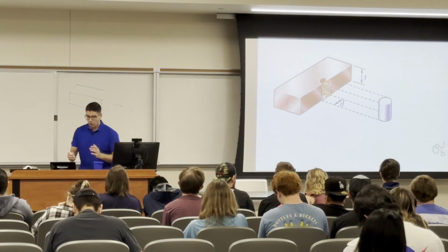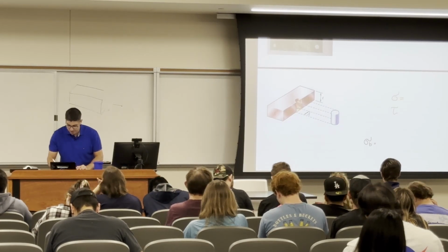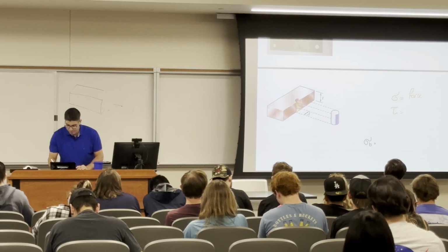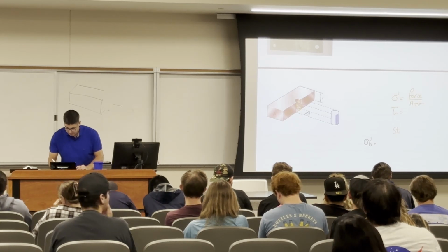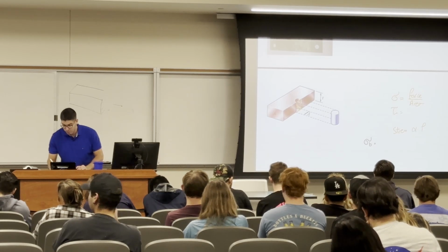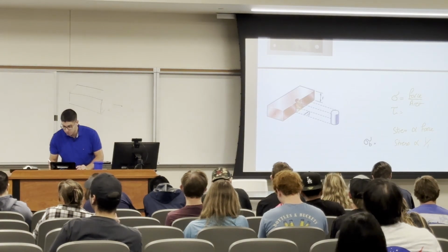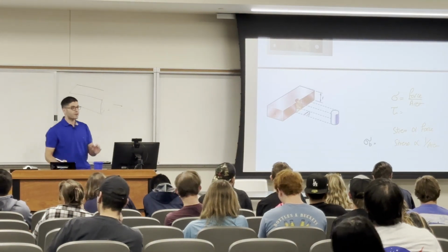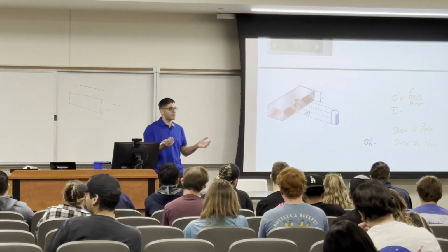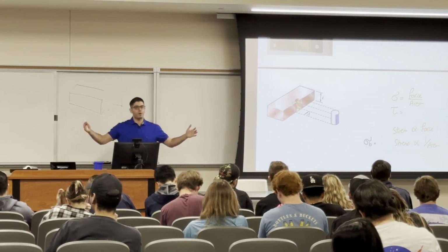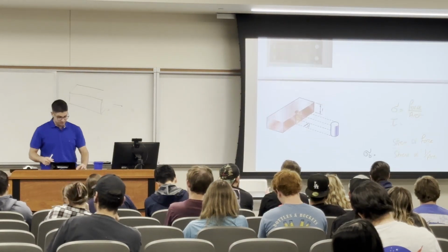Okay? You always look at the equation of the stress. Stress, or even the shear, is force over area. So the stress is directly proportional to the force, and inversely proportional to the area. So if I want to reduce the stress, I need to increase the area, which makes sense. If I want to resist more loads, I want a big diameter, or a big area. Okay?